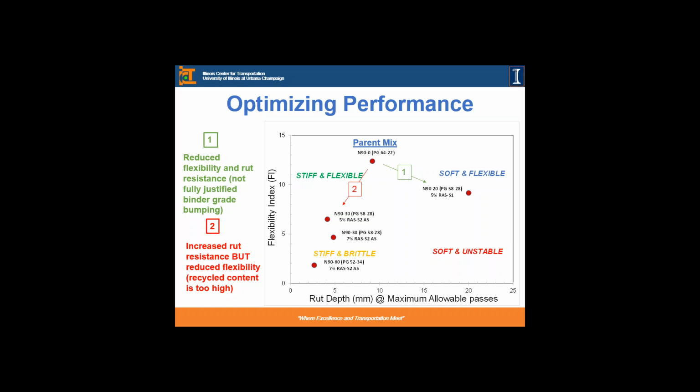This study picked one mix design, so we didn't really change the mix design variables except for the recycled content. But what we had in mind to proceed, the three top things to follow up are the binder content, which is one thing that the designers can easily play with, VMA, and dust content. These are the three things we are targeting in the next phase, or maybe for any other research study, because these are the things that the designer has a chance to play with. And those are the things which we believe will affect the flexibility index greatly.